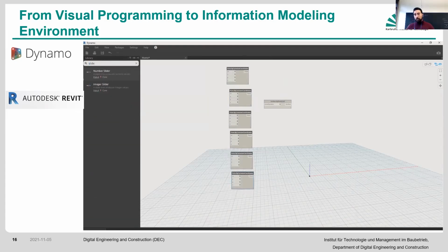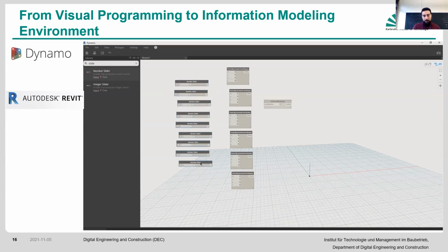For each and every one of these points, now we have a slider number that is related to that. Essentially every 3 slider numbers would provide us 1 point, and then another 3 for another point. We have 6 points, so we would have 18 slider numbers there.